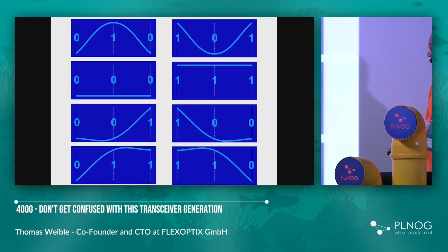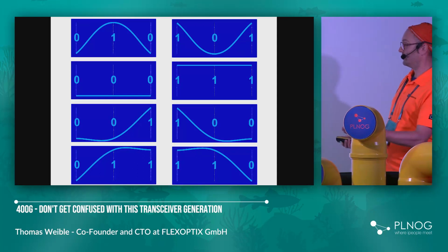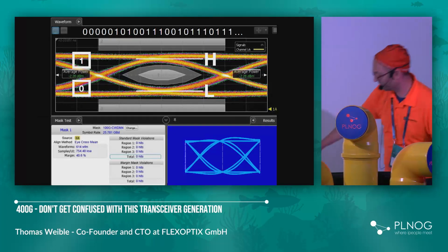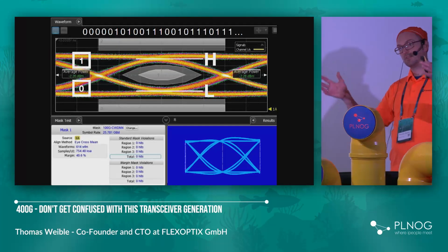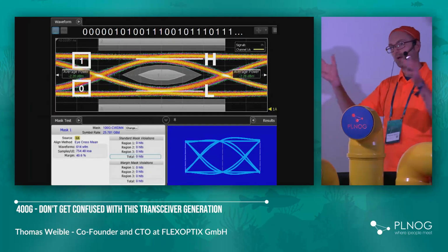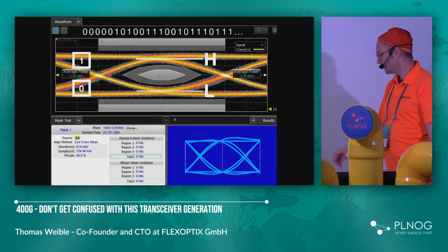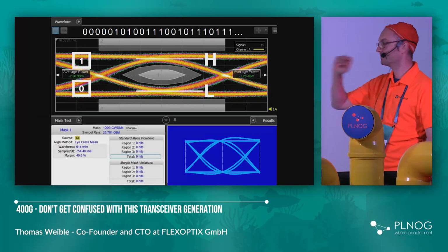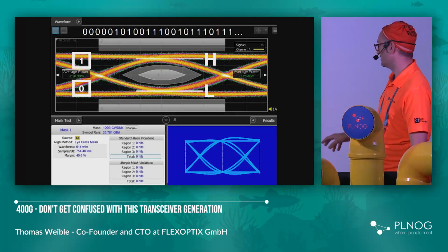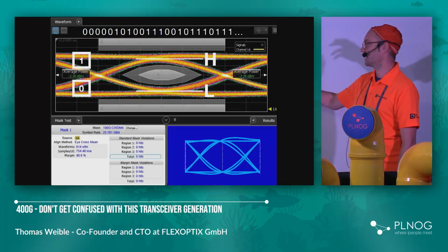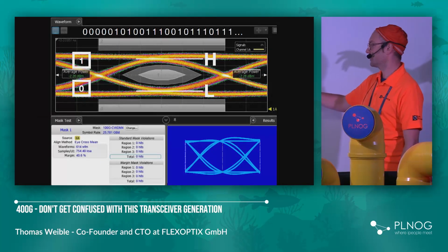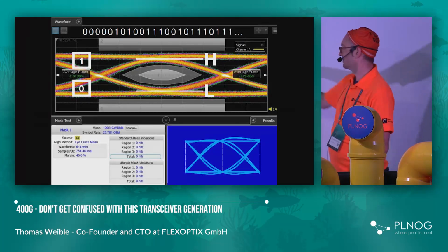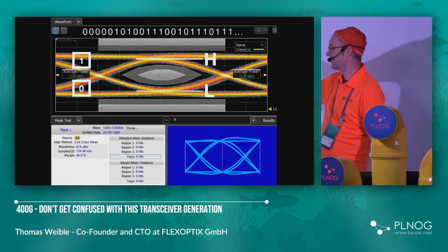Now, how does this come to an optical eye diagram? It is when you combine them. Look down there at all those 8 different schemes I showed in the previous slide. When you overlay them all together, you get something similar to this shape down there, the one in blue. Up there, you actually see a 100 gigabit eye diagram measured with a scope, representing our different states and the events of high and low, having 1 bit.